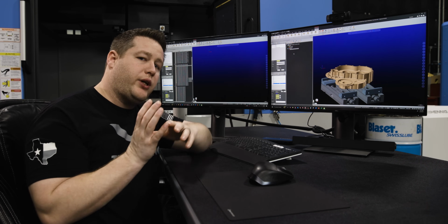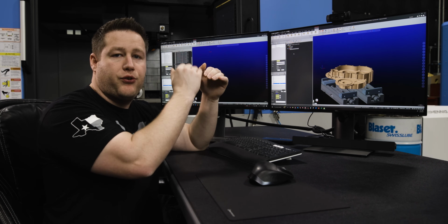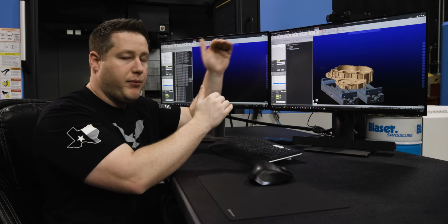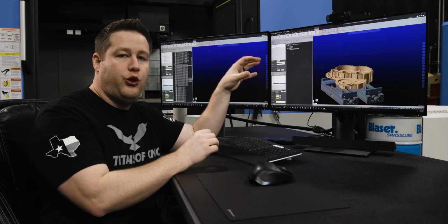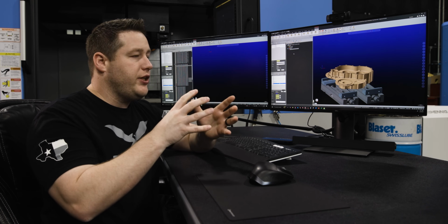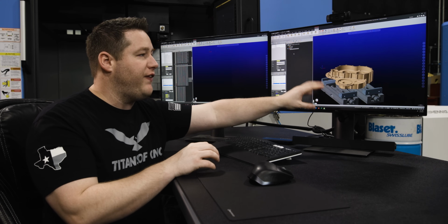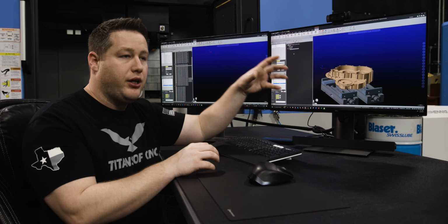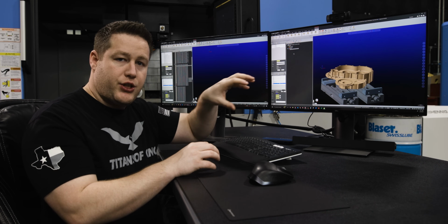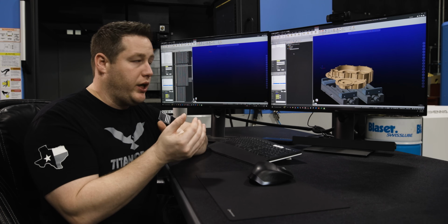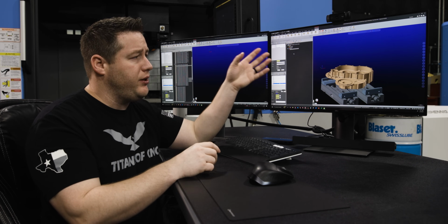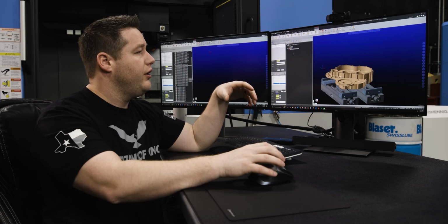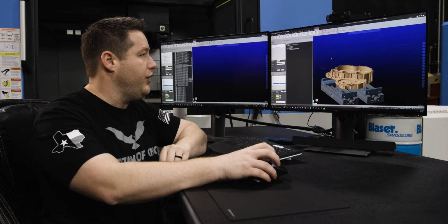Now, it's not going to calculate from that. It will calculate from the stock models it creates from each machine group. But in order for it to calculate properly, it needs that same stock that you use in the first machine group. Other than that, you will create your vises or your fixturing relevant to each machine or each different operation. But for time purposes, we're only going to be machining this first op. So this is all that I have set up.